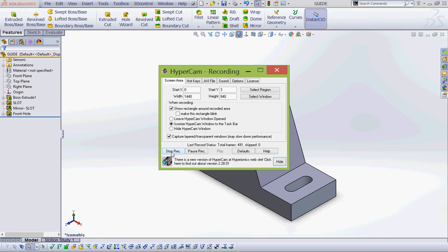Okay, so we want to place a hole on this face right here. So once again, we want to select that face. And do we want to select that top sketch tool or the bottom sketch tool? Bottom. And then notice it went normal to me because of the option that I set. I'm going to draw a circle, so I'm going to use the circle.